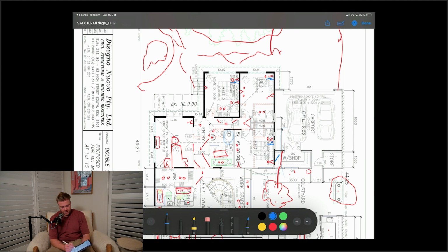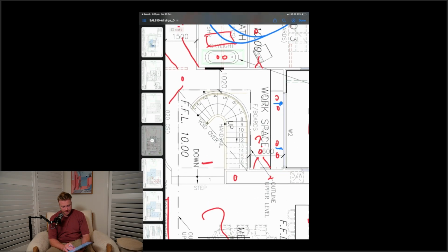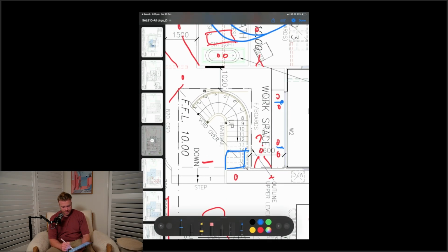So I'd probably be looking at having an access point in this area that'll do this whole space. That hub would probably then do an intercom back to here, and then have some door control in this little central point in the roof there. We'll probably have another data point there. We'd probably go crazy, put one behind every computer in the office. Our main hub, definitely under the stairs as a really good central point. So that'll all come back to that.